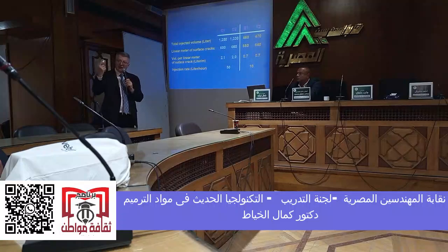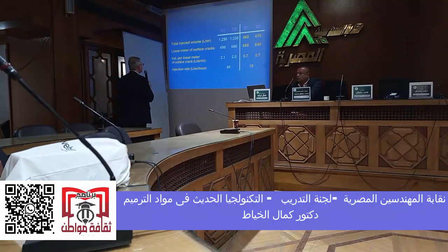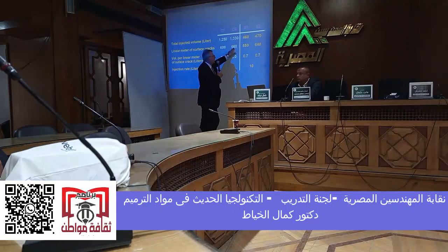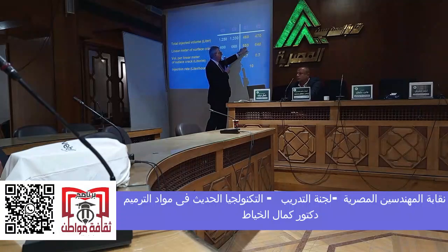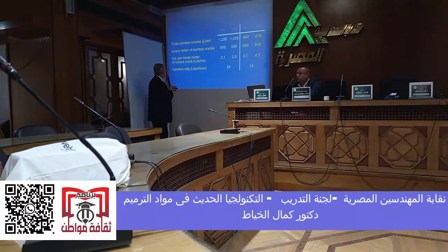And this is very important. You were asking me about the lengths and stuff. So in both bridges, they repaired 600 linear meters of cracks, 660, 650, 640. So the linear meters of cracks are the same, but the volume of grout that was injected per linear meter of crack was 3 times more.